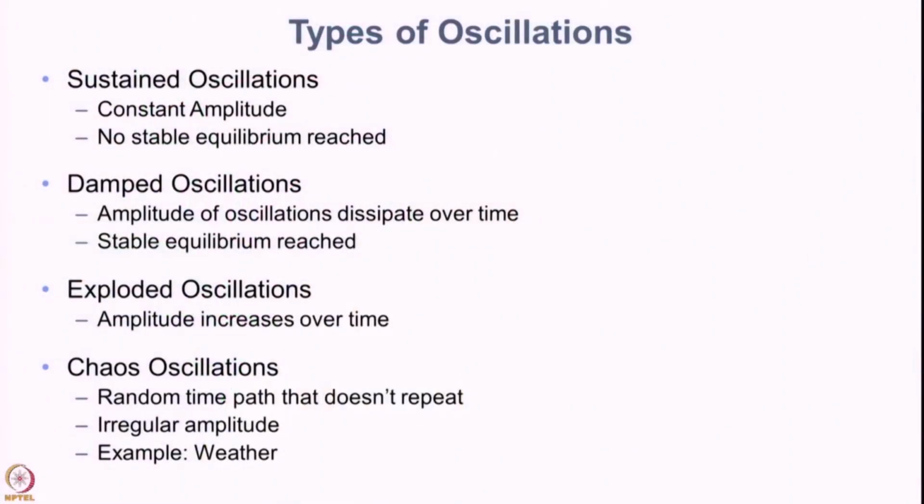So, when you are modeling a system and we understand that there is going to be negative feedback within the system, if there are significant time delays, that will result in oscillatory behavior, and these time delays have to be captured within the model explicitly to get the desired system behavior. With that, let us go ahead and see what are the types of oscillations that we typically encounter.